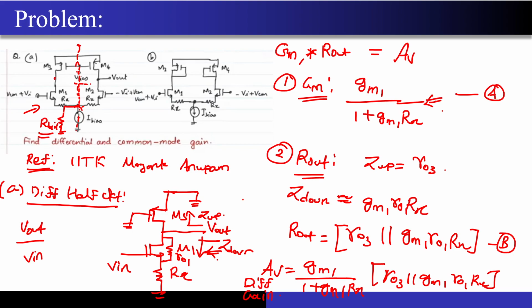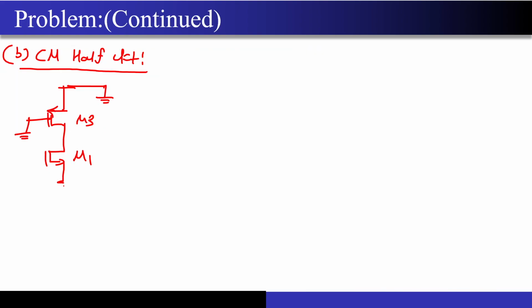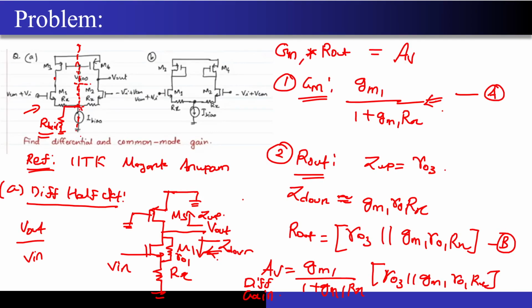Correct. Now on the bottom, what do I have? I have this Rx resistance, correct? Rx. Then what I had done over here, there was a tail current source which I had split into two resistances, correct? Two parallel resistances like this, 2 times R tail, correct? And this particular node came along the line of symmetry. So I have to open circuit this particular point, and there is your Rx that is present over here, correct? So I hope you are able to imagine this. So this R tail I have divided into 2 times 2 R tail, correct? So now along the line of symmetry I have to open circuit this particular point.